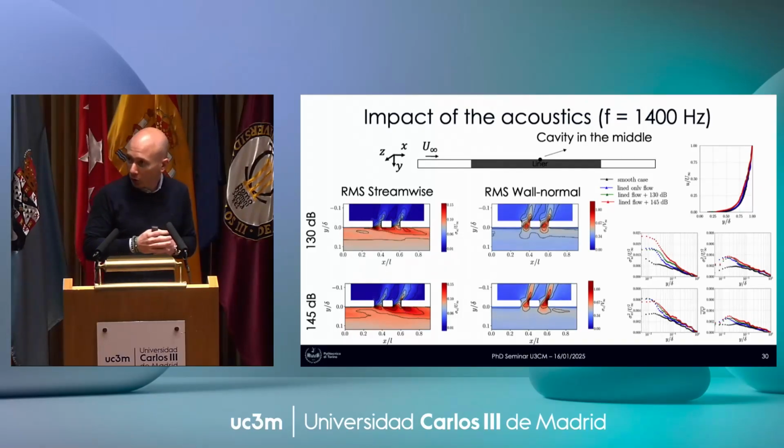And this is also causing, if you remember from the contour plot of impedance, the fact that I see the highest peaks, let's say the maximum and minimum values of impedance close to the surface, because I am including in the estimation of my impedance, where I should have only acoustic information, also periodic fluctuations of hydrodynamic nature at the same frequency. So the two are strongly coupled.